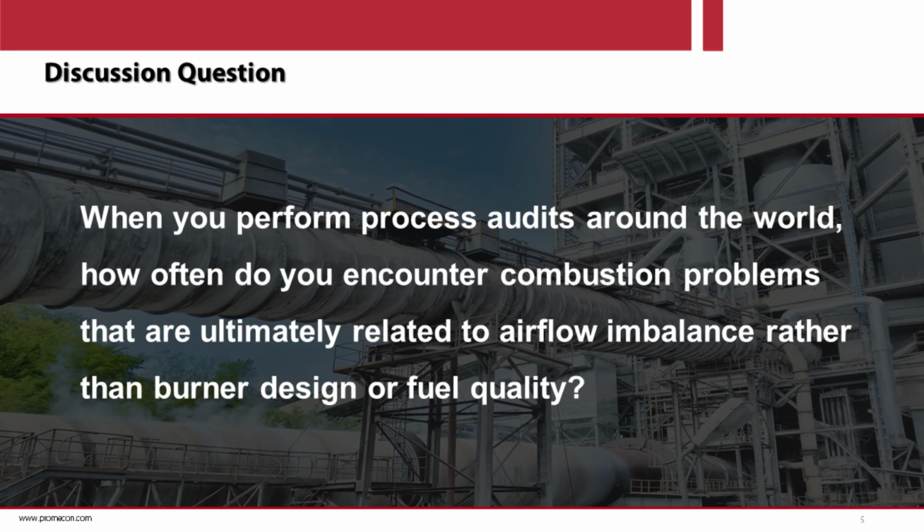But unfortunately, the kiln inlet oxygen measurement is quite unreliable or requires a lot of maintenance because of the dust and the temperature impact in the kiln inlet chamber. For that reason, the probe fails quite often. And in many places I've been, it is even no longer in operation and it is dismantled because of this problem.